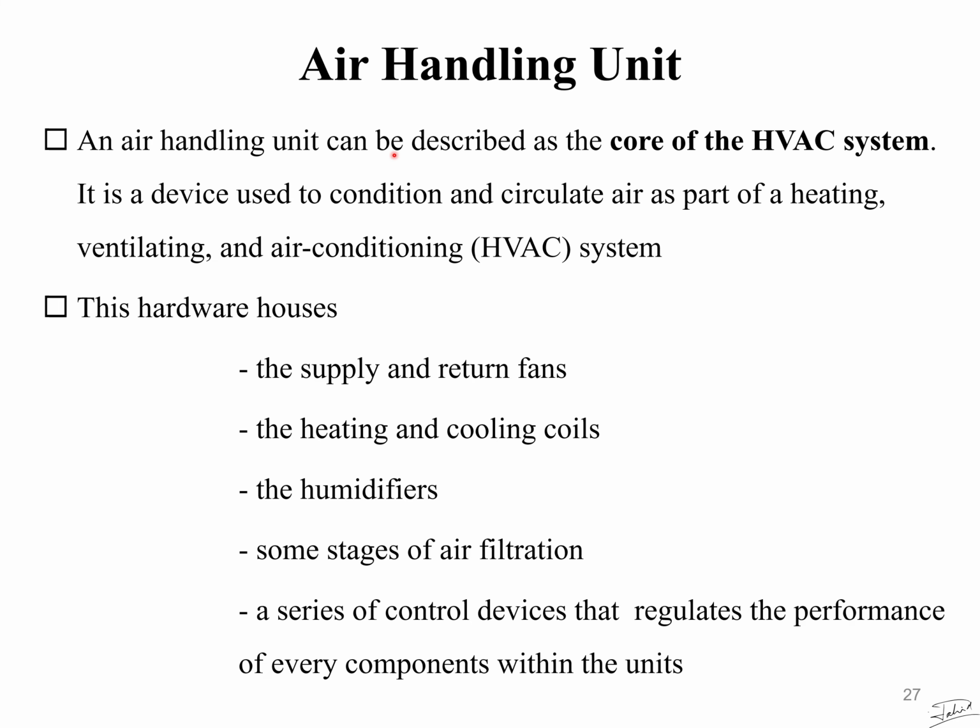Air handling unit. This is the core of the HVAC system. It's a device used to condition and circulate air as part of a heating, ventilation, and air conditioning system. It includes the supply and return fans, the heating and cooling coils, the humidifier, some stages of air filtration, and a series of control devices that regulate the performance of every component within the unit.